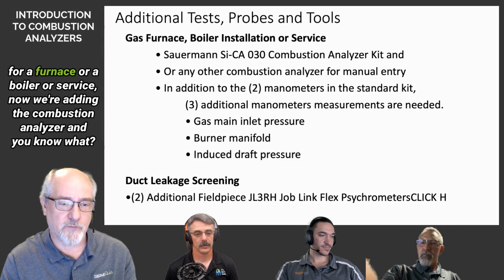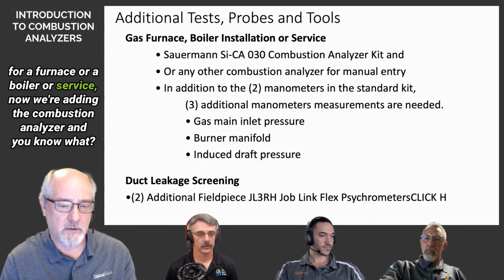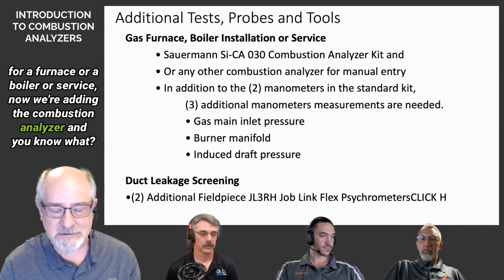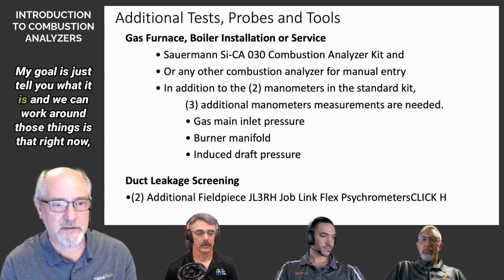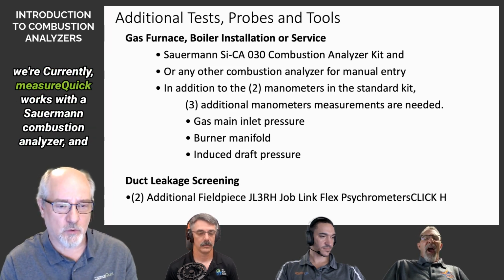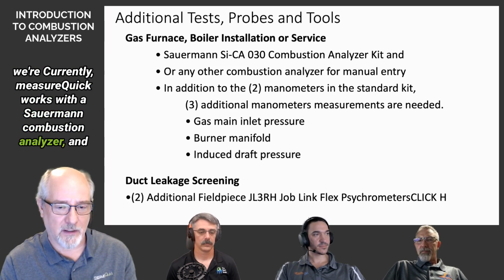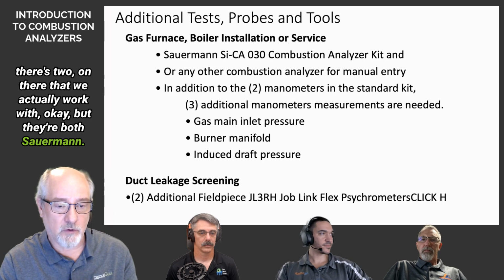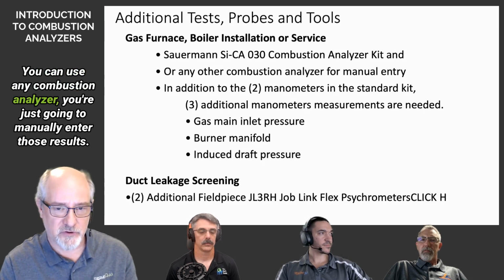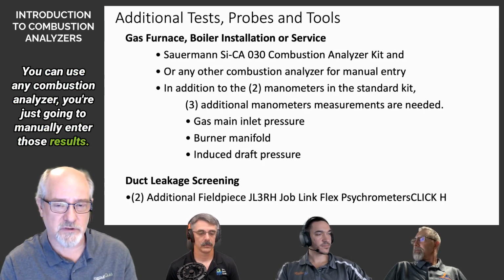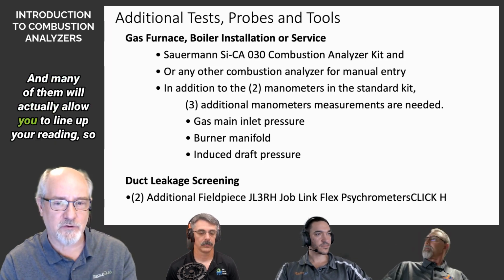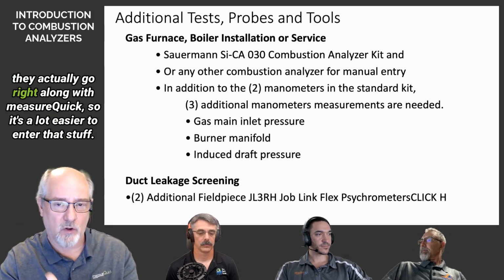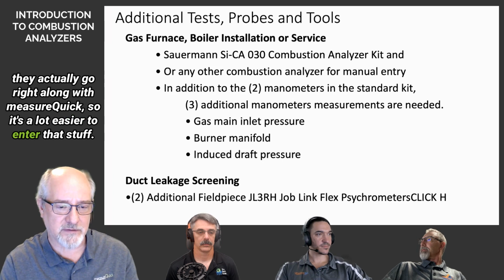Okay. For a furnace or a boiler or a service, now we're adding the combustion analyzer. My goal is just to tell you what it is, and we can work around those things. Right now, measureQuick currently works with a Sauermann combustion analyzer, and there are 2 on there that we actually work with. They're both Sauermann. You can use any combustion analyzer. You're just going to manually enter those results, and many of them will actually allow you to line up your reading so it goes right along with measureQuick. So it's a lot easier to enter that stuff.